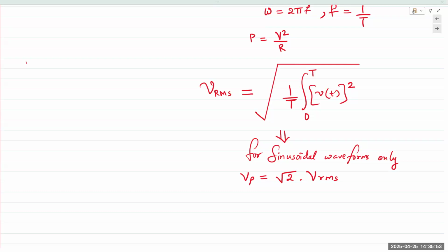Well, when we build electrical systems, they need to be able to handle the peak values because that tells us that at one particular moment in time, the value of that waveform is going to go to plus 170 volts. So your electrical circuitry should be able to withstand 170 volts. Does that make sense to everyone?